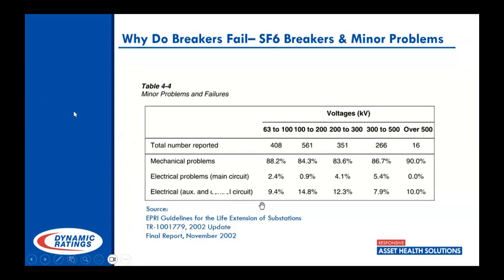So when we go to this next failure, and I feel like this is the one that gets missed in large part. I know a lot of my utility and a lot of utilities, if a breaker opens and there's not a breaker fail or anything to draw attention to that, then that operation is really not looked at. It's just assumed that the breaker operated properly. So when we talk about these, we're talking about breakers that operate. So they do what they're supposed to do, but they're not doing it within the time that's allotted.